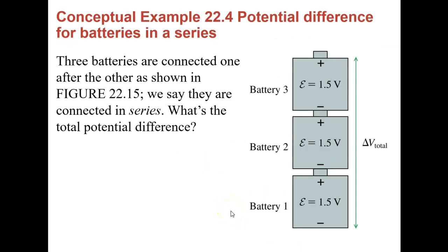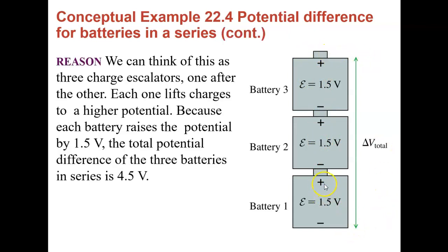So we have three batteries that are connected. We can say that this is called a series, when one is connected to the end of the other one. And if you notice, positive to negative to positive to negative. This is in series, so we have a total potential difference that you just add up. So this gets a bigger potential difference. If you think about when you put batteries into something, typically they alternate the sides that they point to, so the batteries are wired in series, and you have a bigger potential difference. So a bigger potential for charge to possibly move through it.